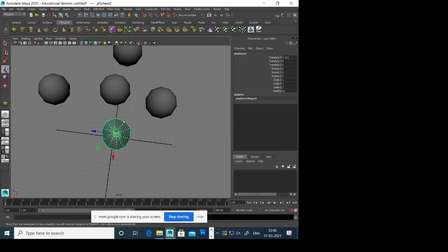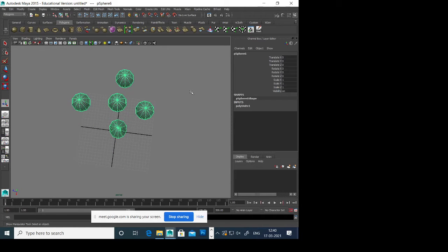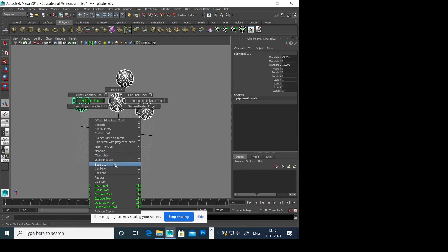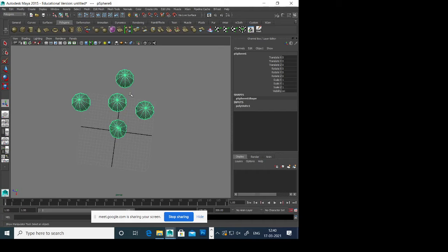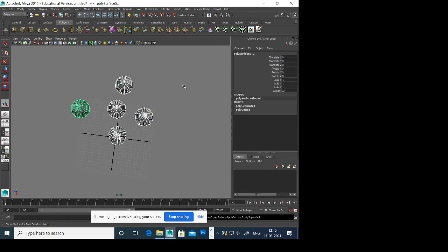But one thing, suppose you want to combine or separate models. Like in Max, suppose you have multiple models you want to combine. You click on Attach, or you use the attach list, select all of them, done. With this option, Attach, everything is attached like this. Or select everything, right click, Combine. Both work the same. Everything is combined. Now if I want to separate, in Max again, select, detach. Select the whole thing, second option, Detach. Everything is separate. All these things are really fast, just one click.